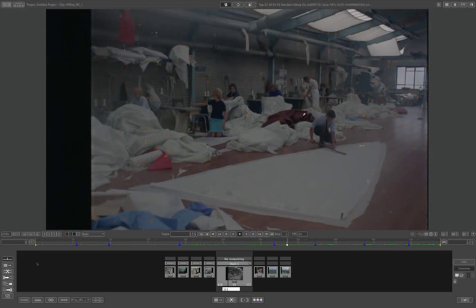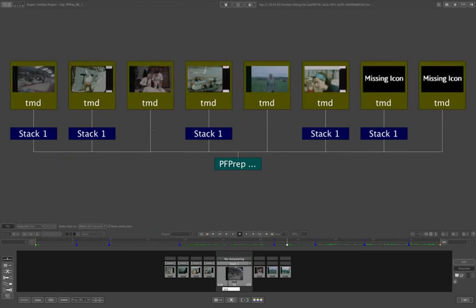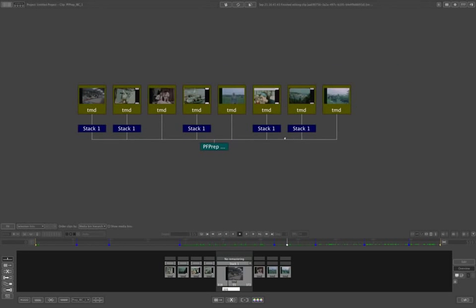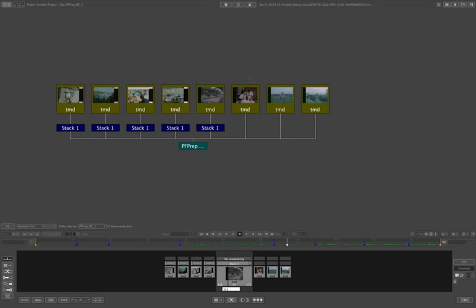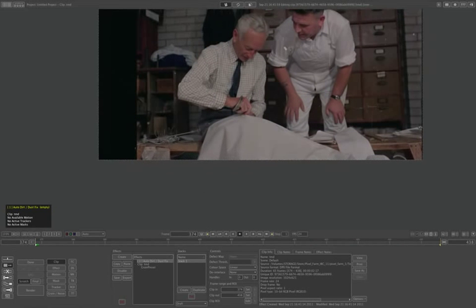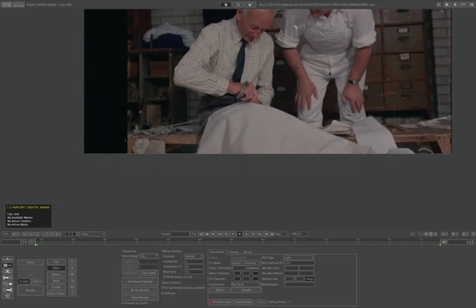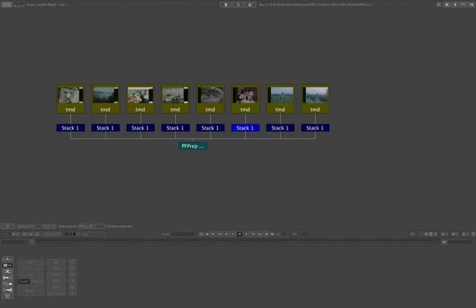Once I finish setting up the automatic dust removal tool for the current shot, I'll close it and go to the Workflow Manager, which provides a graphical overview of my project. I'll use the sort function to sort in order of the timeline, and then copy and paste the effect stack from the first shot to the other shots that require the same effect. Now I'm going to submit these shots to the batch panel for background processing.